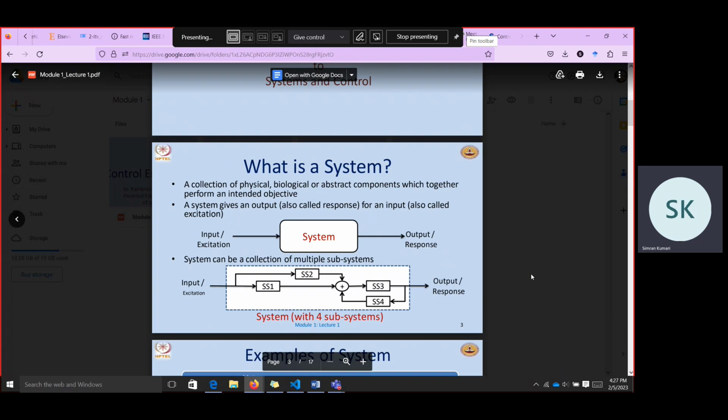So this is disturbance. Now this system behavior will change according to that, and the purpose, like our aim, or we can say the controller's aim, is that it tries to get the desired response from the system. So suppose it is cold outside and the temperature has to be maintained at 25 degrees Celsius. So the heater has to be maintained at that.